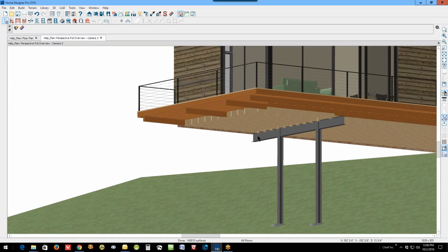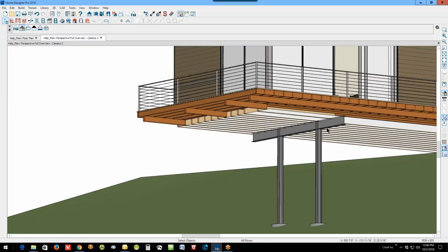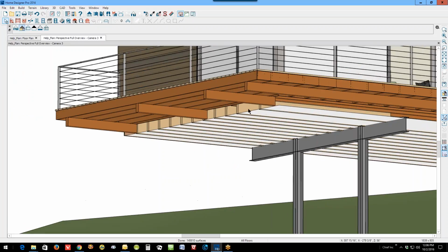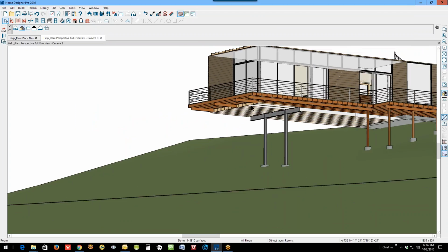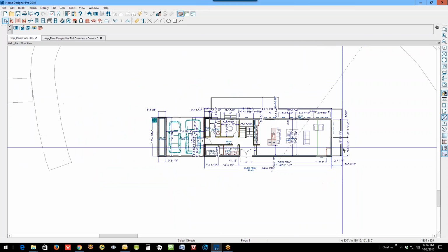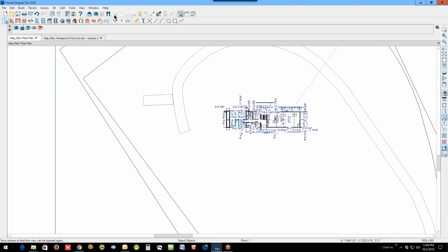I think this view here would be better if we use vector view. Easier to see the lines and so forth. Now you can still see that white stuff there. It's just something you did earlier caused a problem. You're going to need to move the terrain over here underneath your slab. Okay, let's turn your elevation data back on.